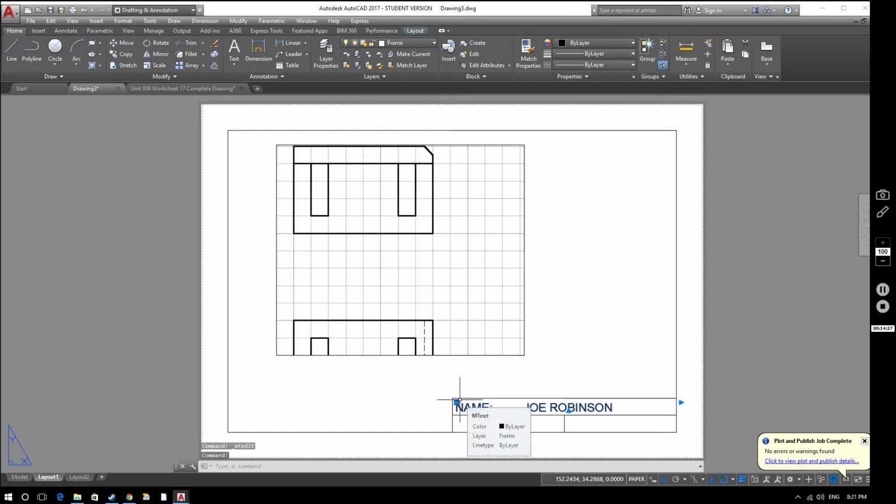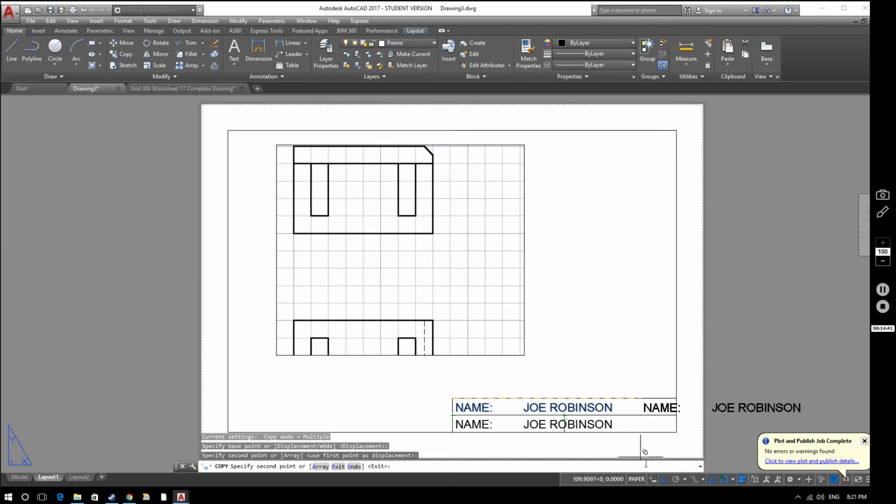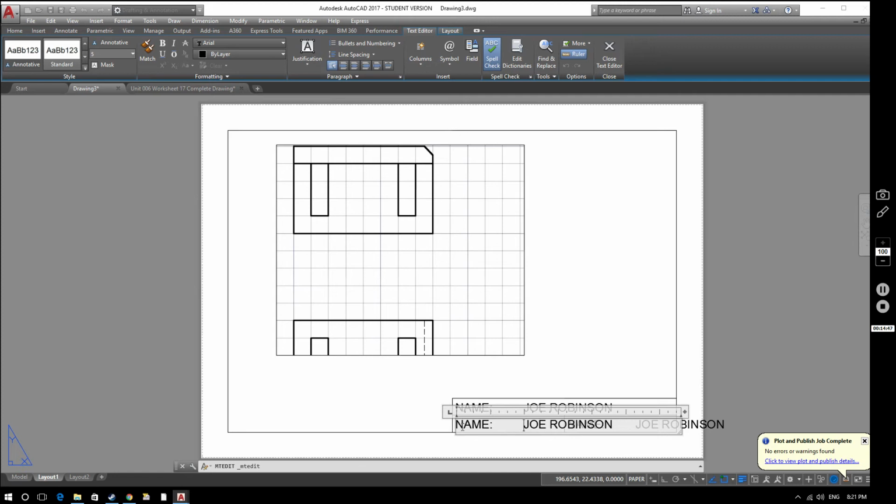In fact, what I'll do is I'll copy that text box, use that as my reference point and bring it down to there. So by using that as my reference point, it lines it up just beautifully there, and then just here as well, although I've still got my ortho snap on, so that will come off, and we'll pop it there like that. Edit the text in here.